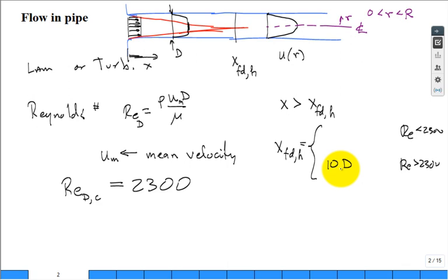This is one of the little things, hopefully, that you remember, because if you get out there and you have to work in the field with flow meters and whatever else, heat exchangers and other things, the technician will put a flow meter 2 diameters right away from some disruption. And it's like, right away, it's terrible. Okay, so there's a good equation to remember. 10 diameters, turbulent flow in a pipe, that's the length required to become, again, fully developed.